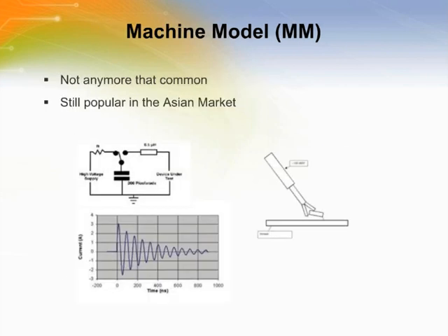Machine model testing requires a specially designed load board which interfaces with an automated high pin count ESD tester. Each pin is tested with high voltage and high current ESD shocks, while other pins on the board are held to ground. Essentially, each pin is zapped with respect to groups of independent power and ground supplies, as well as each pin being zapped while all the other I/O pins are grounded.